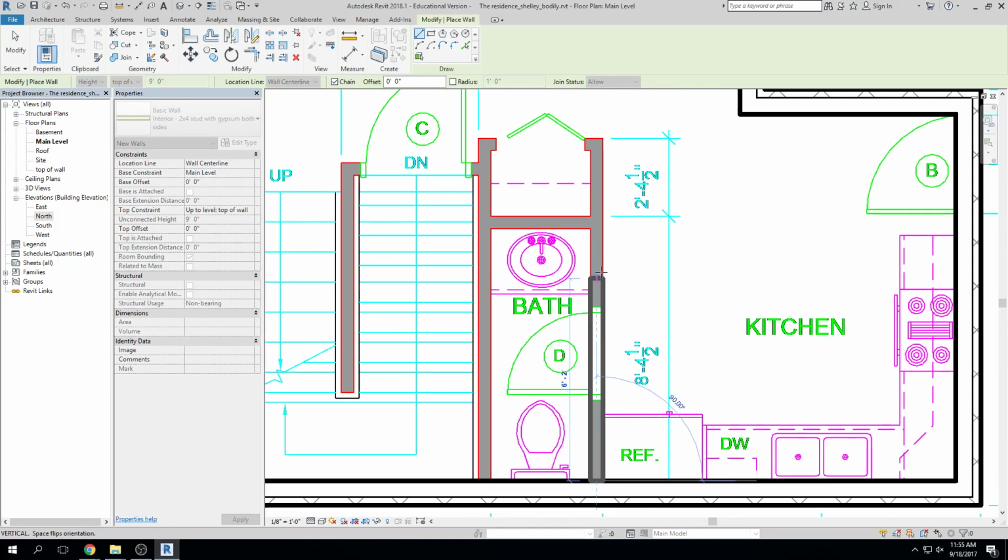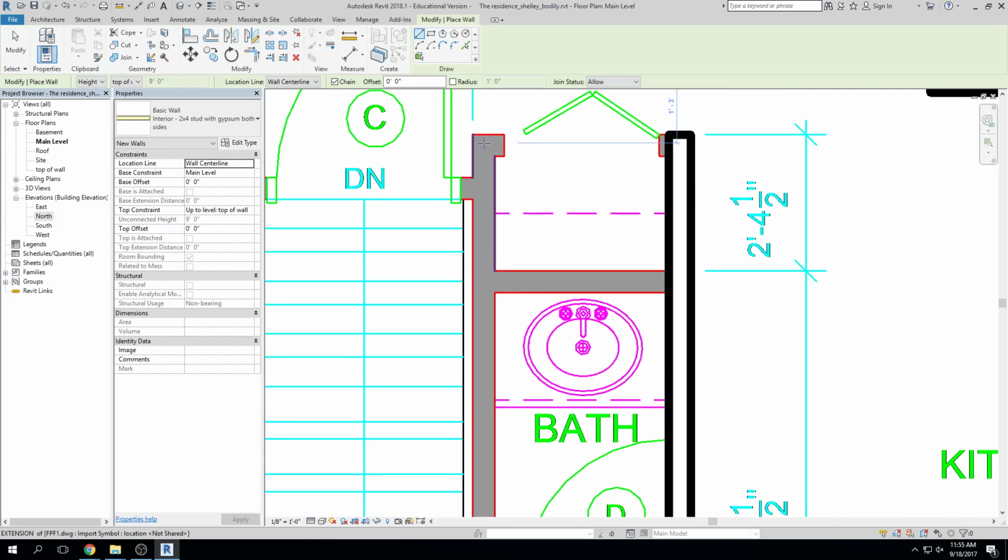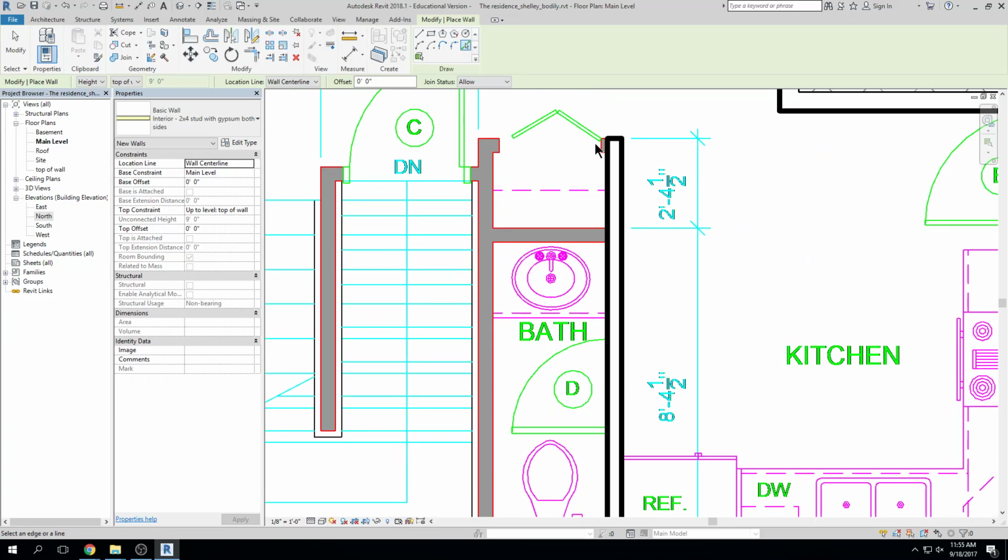And again, I'm going to go over the top of the doors all the way to the end here. Click, escape. Then I'm going to go to the center line of this wall, which I'm trying to grab. It's a little hard. Maybe drawing is not the right tool. Maybe I go to the pick. Click. Zoom out a little. Ooh, it's hard to get that center line. Maybe I might have to align it after I'm done, right? The pick only wants to grab, because it's a CAD file, one side or the other. So I go back to the line tool. I draw as much as I can.